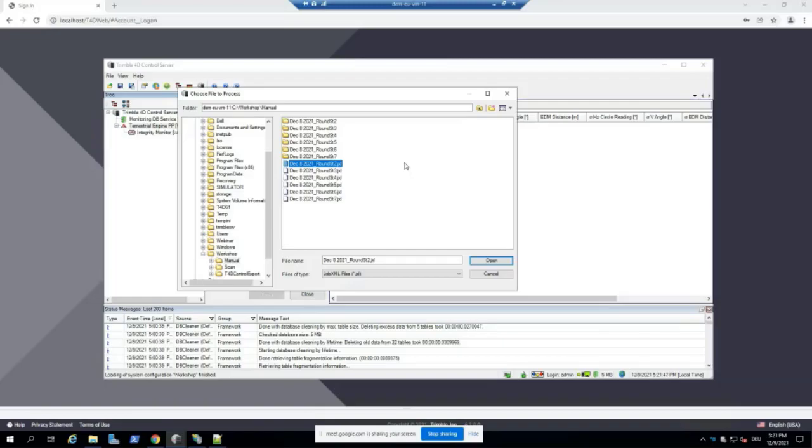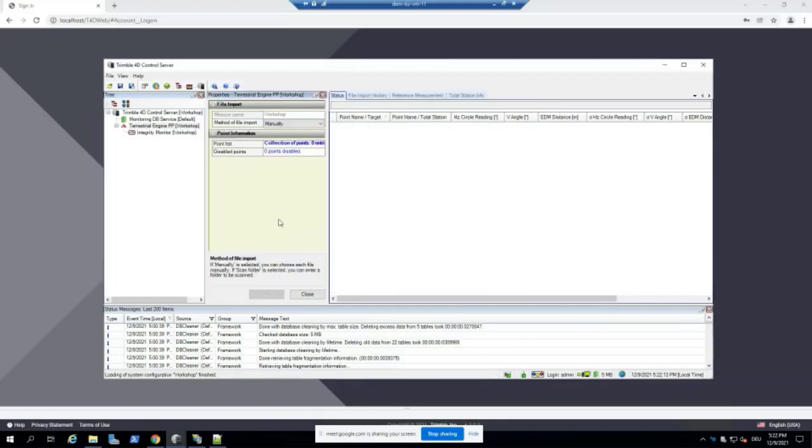That's also another big benefit of T4D Access in combination with SX instruments. It's not about observations only. So you can import observations plus the images that you have taken with the SX instrument before using Trimble Access Monitoring, right? The only thing you need to do in T4D is select the job XML file. And that's what I'm going to do now. So I select this one here, and then I say open, and that's it, right?